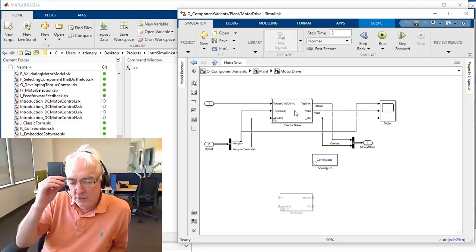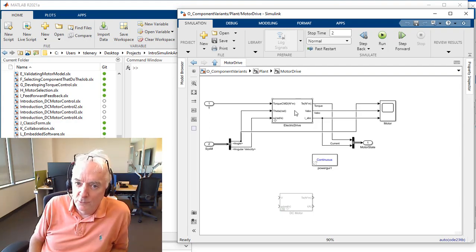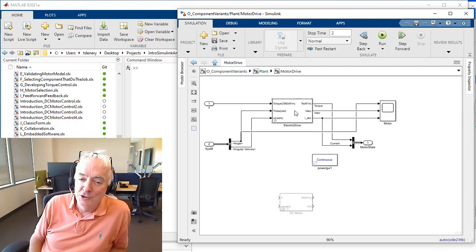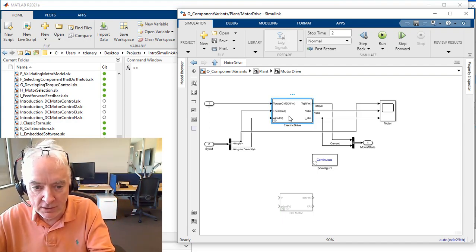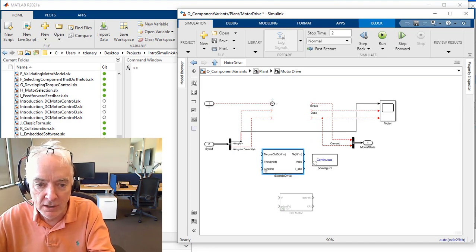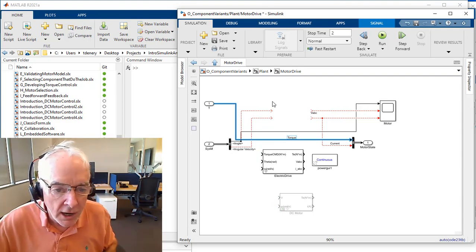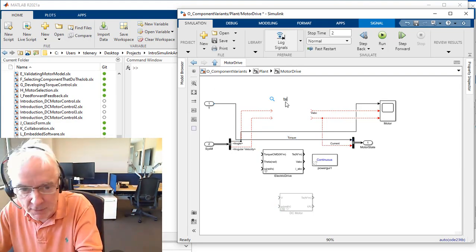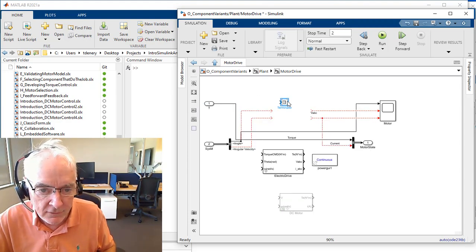And in a way, the reason we can work around this as well as we can is because electric motors work so well, all right? And if you choose the appropriate electric motor, they're very good at delivering the torque that you've asked for, right? And so that's pretty much the nature of the approximation, is we're going to just deliver the commanded torque. All right, and I want to maintain my interface so that when I'm ready, I can put that motor back in.